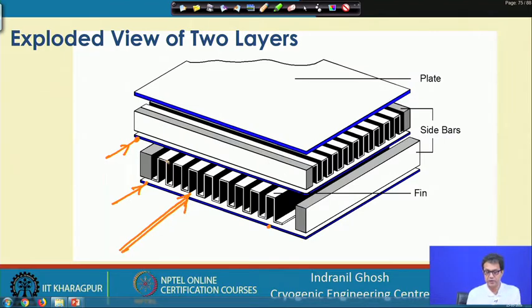These are the extended heat transfer surface area fins, and now imagine we have put on top of it another layer, where this is the plate, the primary area separating this fluid from mixing with the fluid entering from this end, and we have another separating plate on this side.